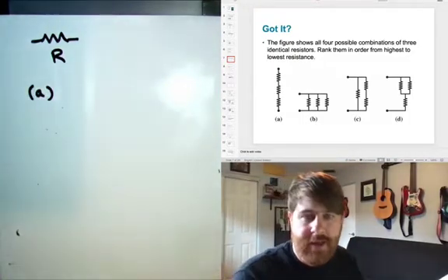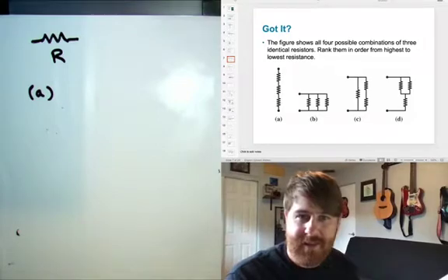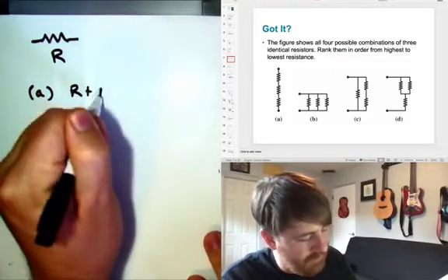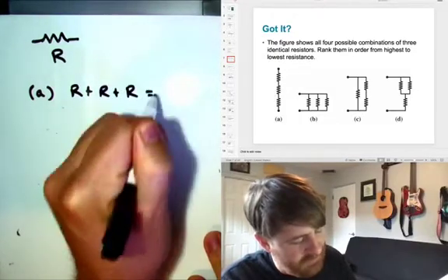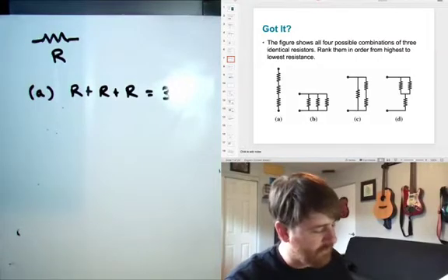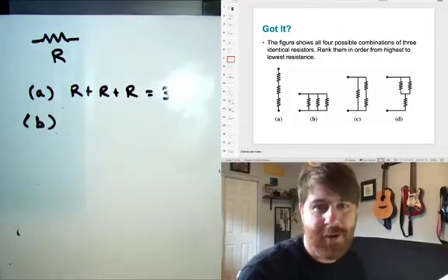All right, so now what about for A? Well, are they in series or parallel? Yes, they're in series. So that means I need to add them up. This is R plus R plus R, which is 3R. Okay, what about B? Series or parallel? Right, parallel.